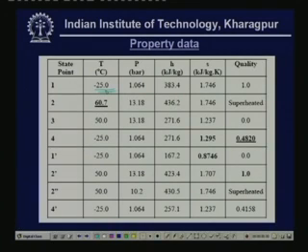This is the exit of the evaporator or inlet to the compressor. We know this temperature and quality. So, we can find out the saturation pressure, and then we can find out the enthalpy and entropy from the P-h chart or from the T-S chart or from any other database. Next, point 2. Point 2 is the isentropic compression. We know the pressure, which is the saturation pressure corresponding to 50 degrees centigrade, and we also know that it is an isentropic process. So, the entropy is the same. So, these 2 are known to us.